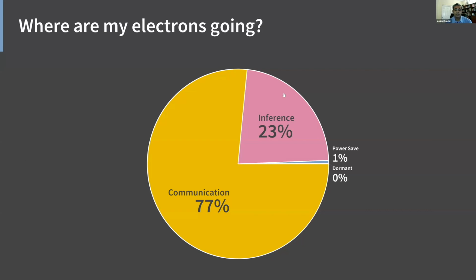I mean, this is really the bottom line, right? You can't do much about it at this point. The communications is what it is. This is assuming a well-optimized system. By increasing the frequency of sending data, you may not really affect this too much because a lot of it is just spent sleeping. I tried making this once every half an hour instead of once an hour, and it didn't have too much of an impact. But it really depends also on how much data you're sending. So I think you have to go through the details to come up with an answer for that.